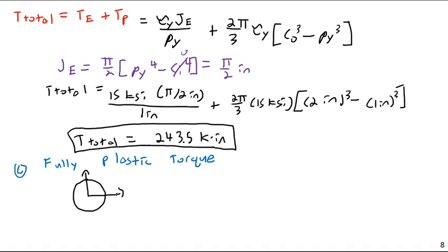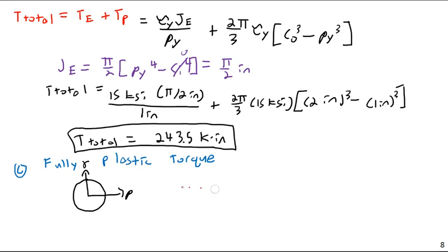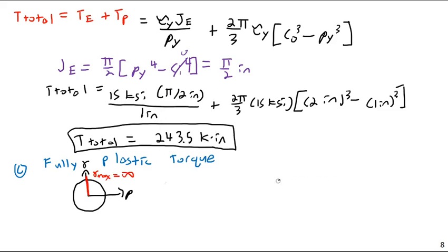We're going to have this rho and gamma, but this is just going to be a vertical line. This is just fully yielded all the way through. So gamma max equals infinity. It will twist as far as you want it to, because it is completely yielded.